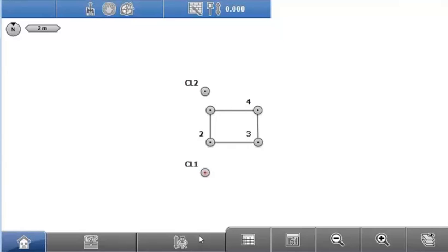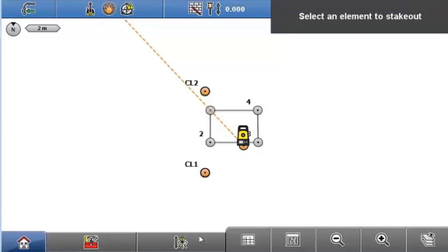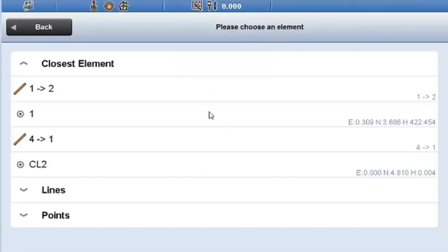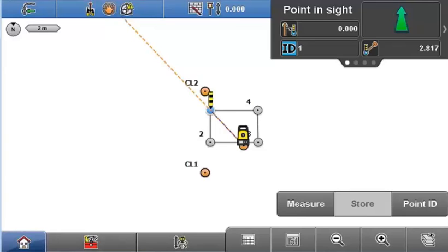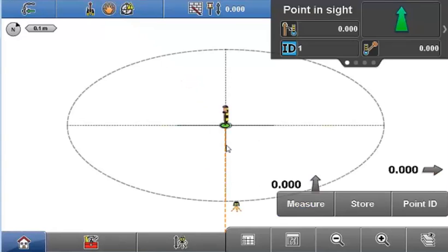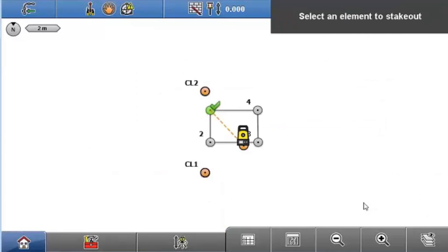And you can probably hear that my total station is moving, and it's pointing in the right direction. So it now tells me where I am once I measure to it. There we go. So obviously I'm going to be right on the mark there at 0, 0, but you can see that it then switches to the bullseye view again. It gives me a little green point here saying that I'm within the tolerance. So I can store that point comfortably, and I get a green tick.